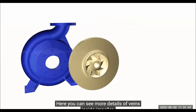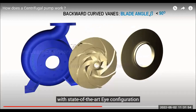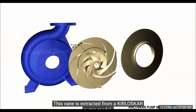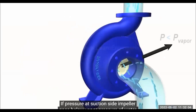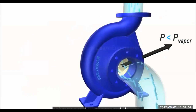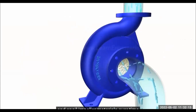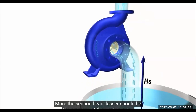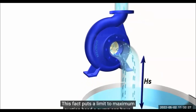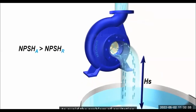Here you can see more details of vanes inside impeller. They are backward curved vanes with state-of-the-art eye configuration. This vane is extracted from a Kirloskar pump model. If pressure at suction side of impeller goes below vapor pressure of water, a dangerous phenomenon could happen. Water will start to boil, forming vapor bubbles and spoil impeller materials over time. This phenomenon is known as cavitation. More the suction head, lesser should be the pressure at suction side to lift water. This fact puts a limit to maximum suction head a pump can have. Careful pump selection is required to avoid problem of cavitation.